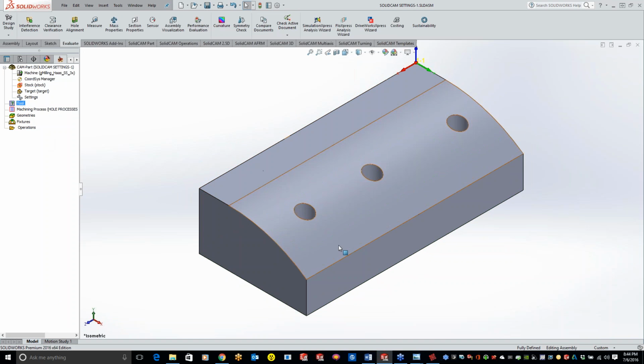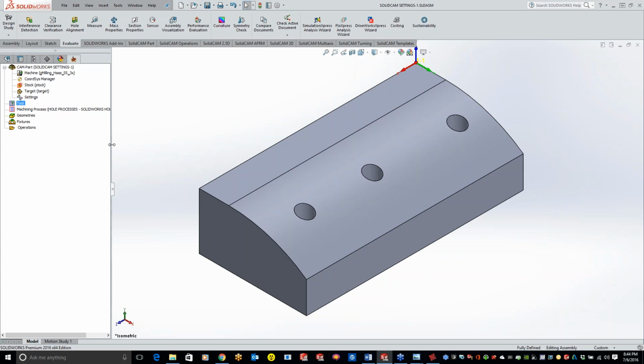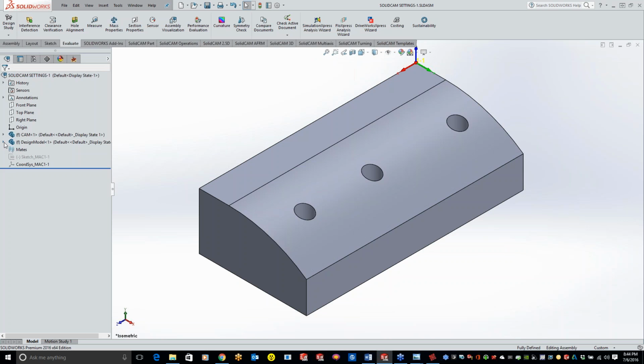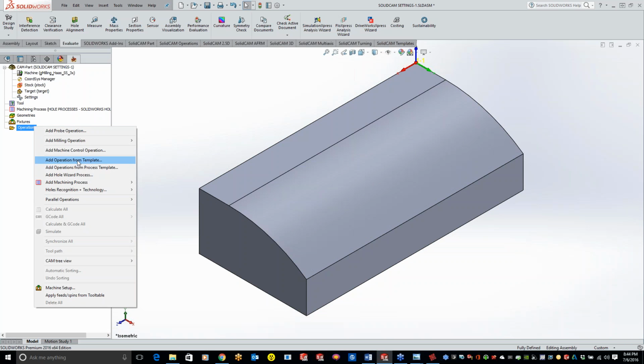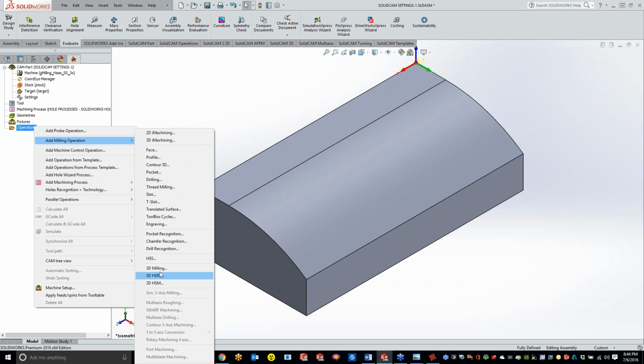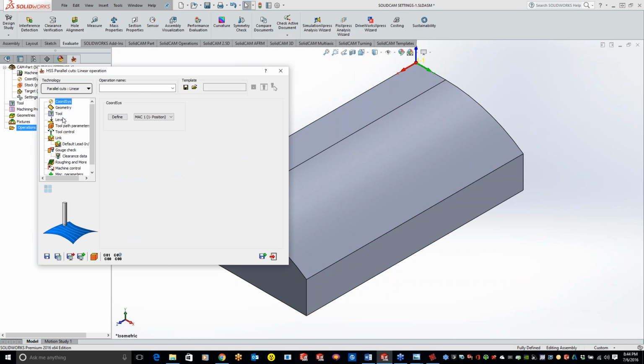So now you'll see I got it set to user demand. On a particular part, if you decide to make the changes, you can change it in the settings right here, and I'll go over that shortly. But let's say you want to just hide that last cut extrude. I can come over here, and nothing's going to change. You'll see I have no stoplights popping up. And now I can add my HSS.